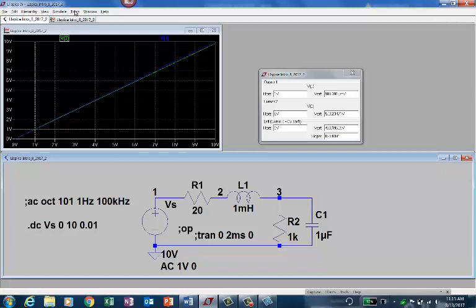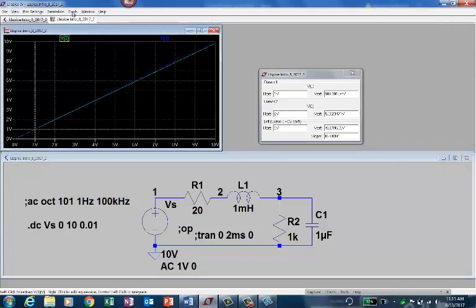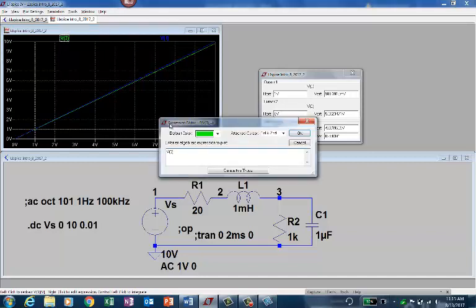If you want to find out the current and power on this sweep, by the way, you can find out the current through the voltage, and also multiply the power of that resistance. You can find out I of R2. You can make a product of the voltage and the current, which will be the power across the resistance R2.